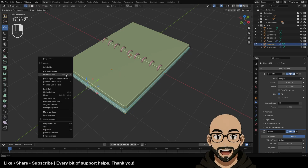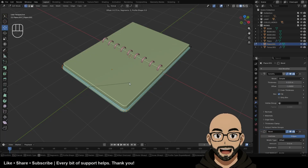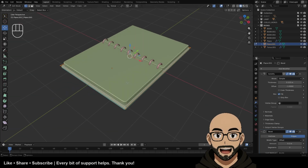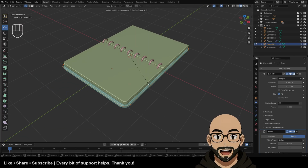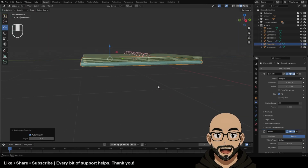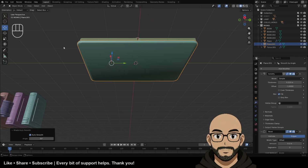Just select these two edges, bevel edge. You can kind of round this off. Actually, you want to select all four because this is not mirrored. You want to select all four bevel vertices. Shade auto smooth. Now we want to kind of split down the middle.